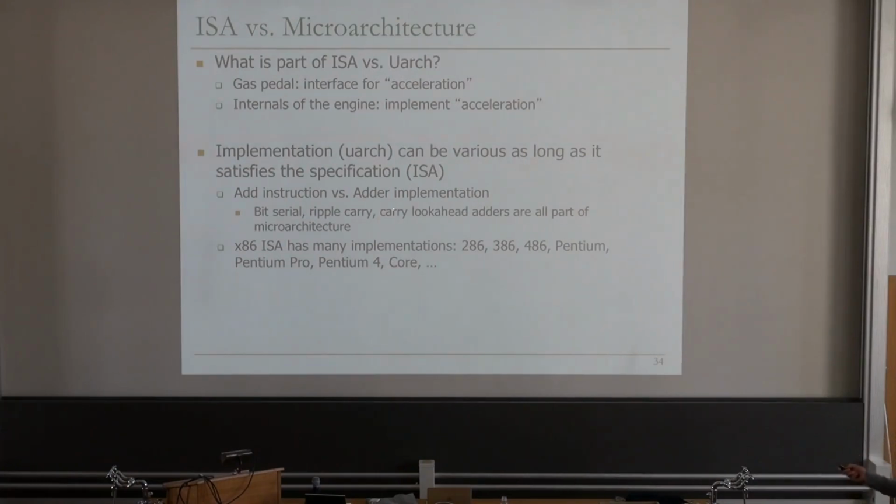Now people have designed many, many other adders like carry look ahead that try to parallelize the computation, assuming some carry. So clearly there's a huge trade-off between these different adders, even if you look at a simple thing as an adder, right? And this is all microarchitecture of the adder, basically. You don't expose the carry look ahead behavior or ripple carry behavior or bit serial behavior. The user just issues an add, and the add happens.